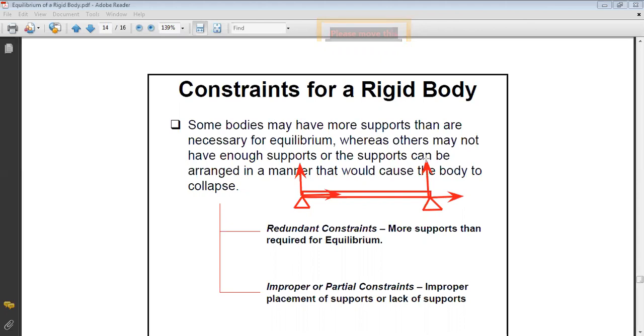So by using just statics, equilibrium, you cannot find the 4 unknowns because you can only write 3 equilibrium equations, okay? Of course, 3 equations that are not repeated. You can write 100 statics equations, infinity of statics equations. So if you choose 100 points, you will say sum of moment about A equals 0, sum of moment about B, about C, about D equals 0. But at the end, only 3 equations will be independent, okay?